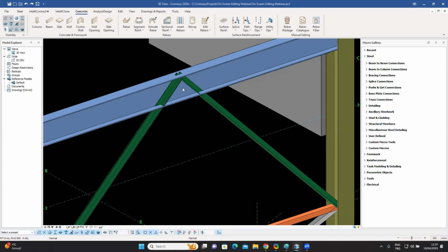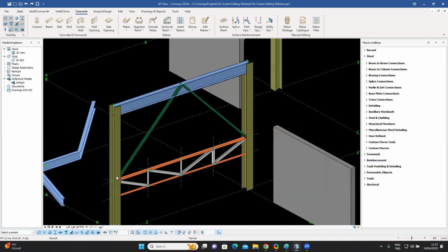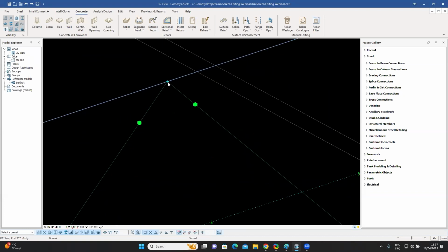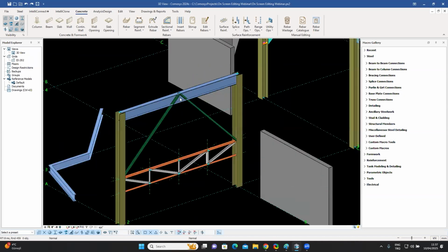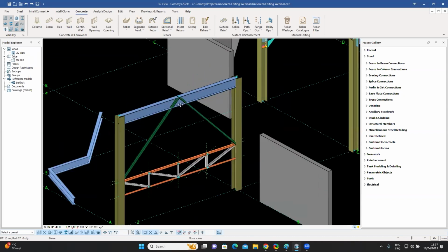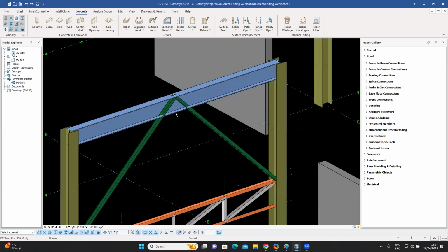But the problem with this is if I enter it at the middle of the beam, then the finite element model, which can be seen by doing, for example, Alt-D, you can see the finite element model is connected at the moment. But if I move the braces down physically, the finite element model will be disconnected. I don't want to do that. So I have another handle which doesn't change the formal finite element model, but moves or offsets the frame